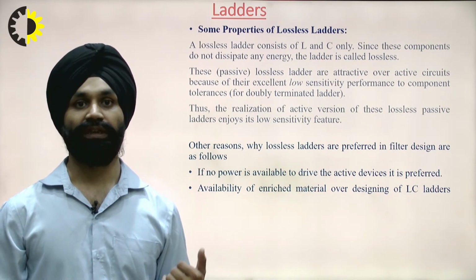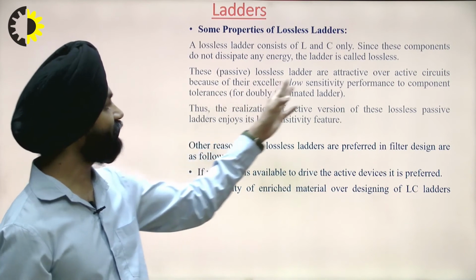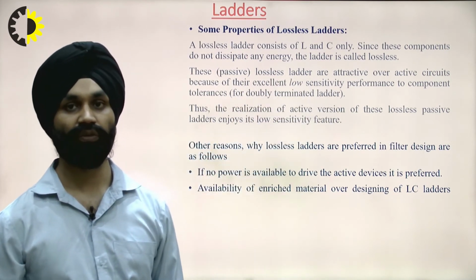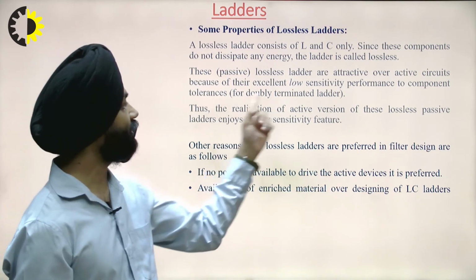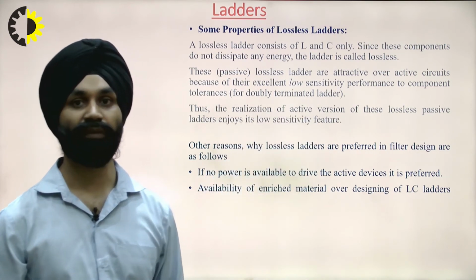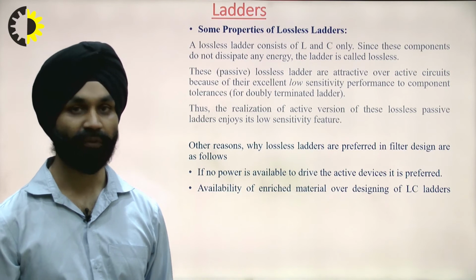So this passive or lossless ladder is used over active circuits because of its low sensitivity performance to the component tolerance.